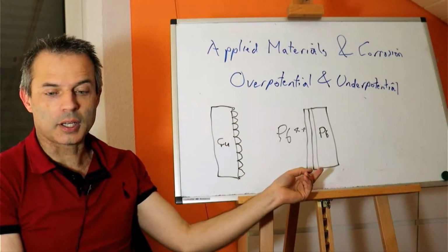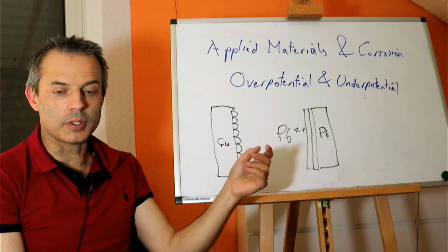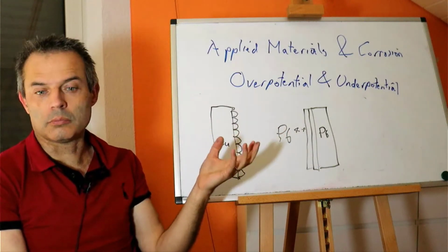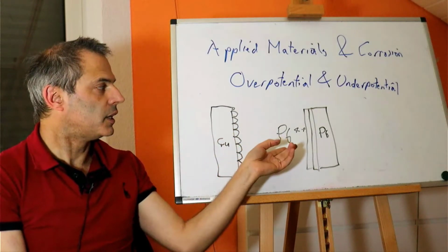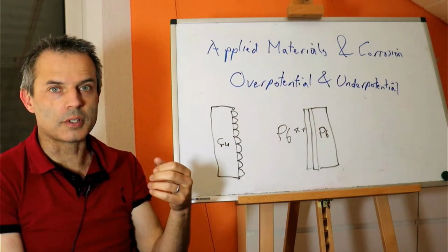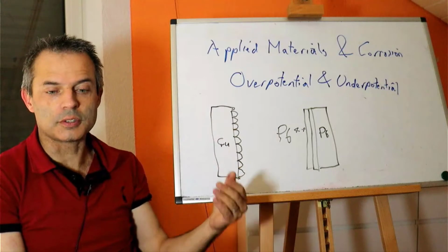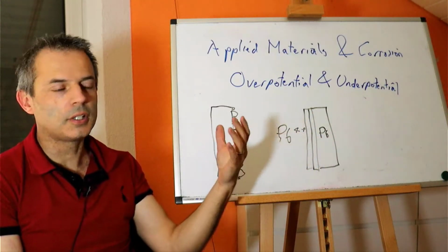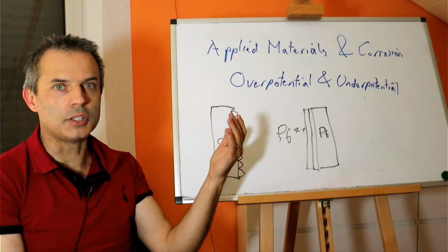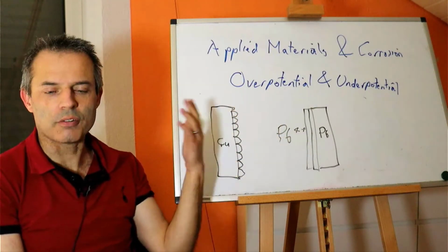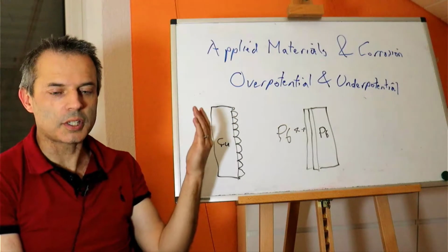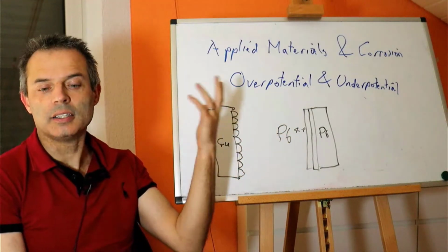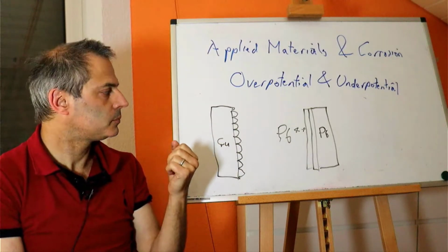So we take a lead electrode and we're trying to coat it with lead from solution. It's got relatively low activation energy. The lead ions can join on to the surface of the lead, and this new surface of lead looks exactly like the old surface of lead, so we're not making anything different. So the total interfacial energy is staying the same. If we make it rough, then it's costing us some surface energy, but if we're increasing it gradually as a flat layer, we're not doing so.